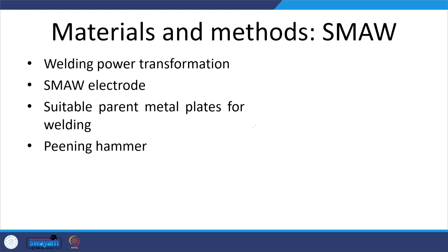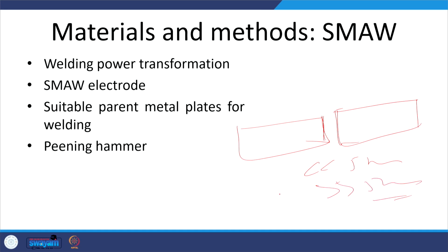When we have plates like this, if the thickness is less than 5 mm, then even square edge preparation is fine. But if the plate thickness is greater than 5 mm, then depending upon the thickness for butt welding, the grooves are prepared in different ways. Okay, like single V, single U, a single bevel like this, or single J like this. So, J, V, U or bevel, these are the kinds of groove edge preparations for developing butt joints. Okay.